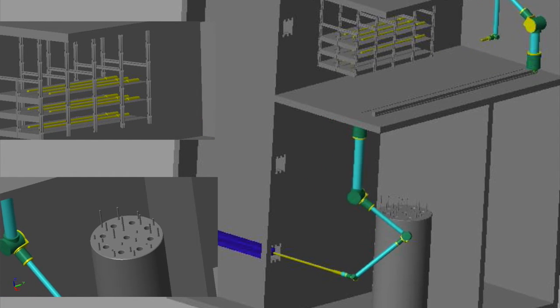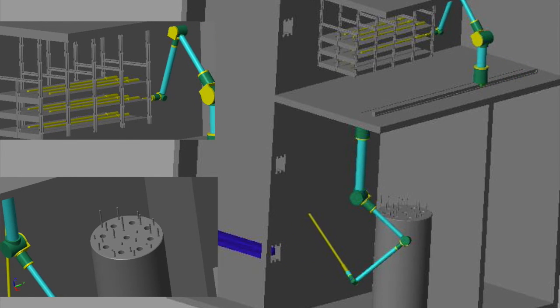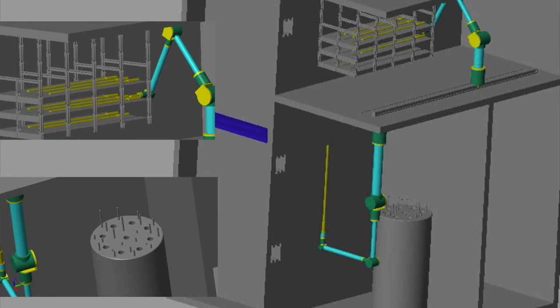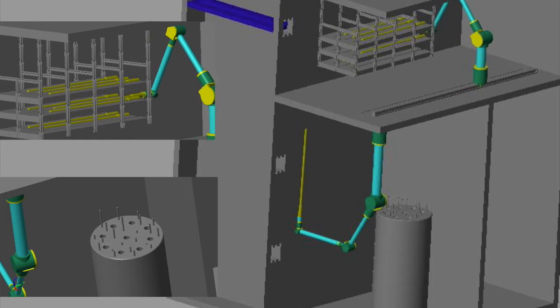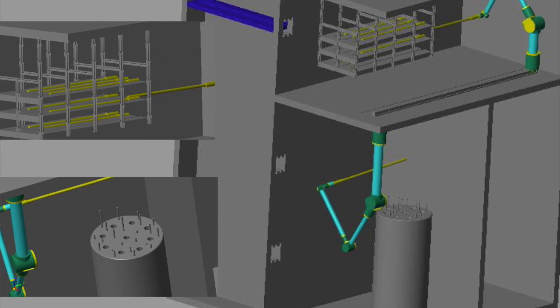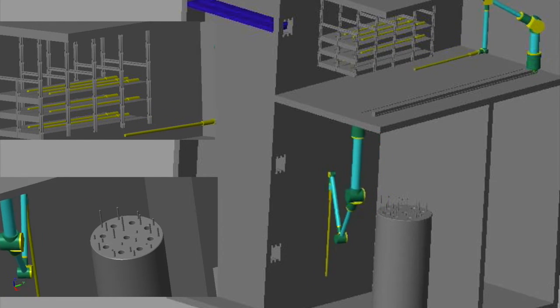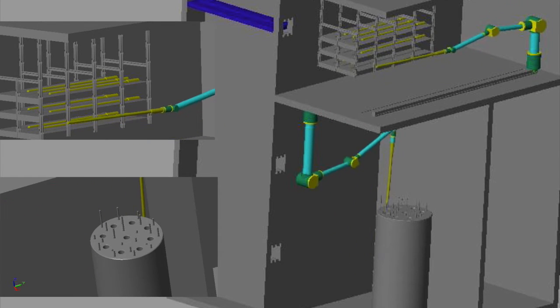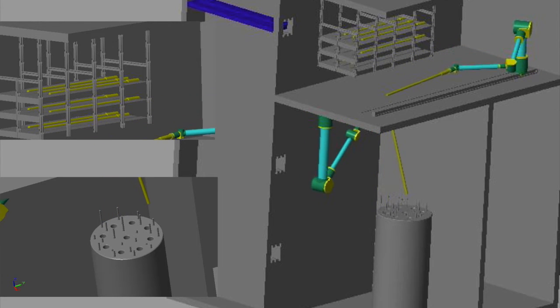The inverse kinematics were calculated at key points along the trajectory. This was done using the robotics toolbox functions ikine and ikunc. Once we had the joint orientations at these key points, time-dependent trajectories could be generated between them to fill in the points along the path. These time-dependent trajectories were created using the robotics toolbox function jtraj.